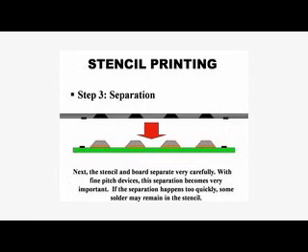Step 3 is separation. The stencil and the board are separated very carefully. With fine pitch devices, this separation becomes very important. If the separation happens too quickly, some solder may remain in the stencil, causing defects.